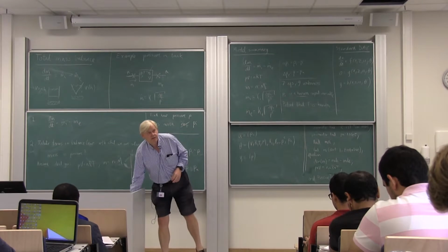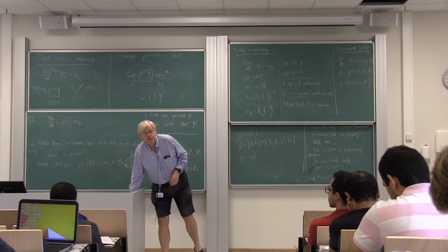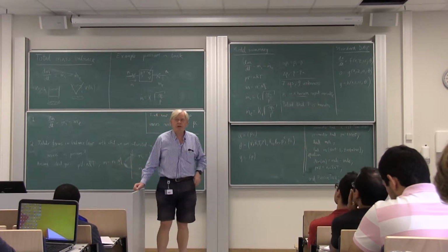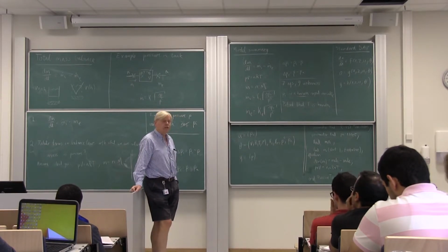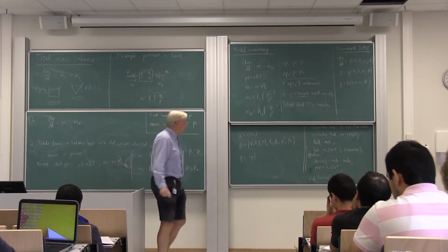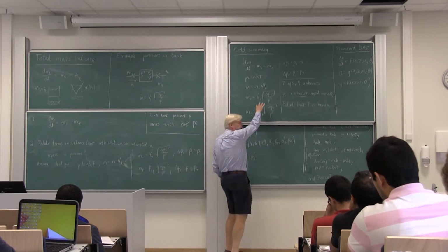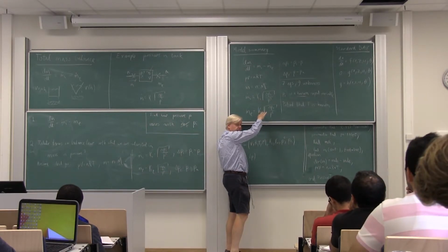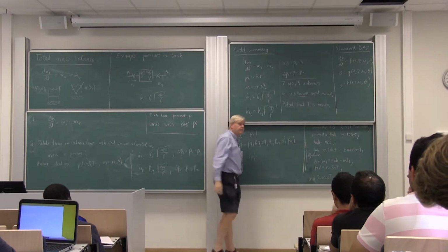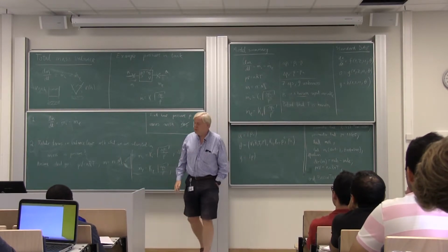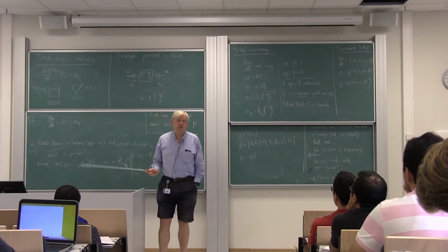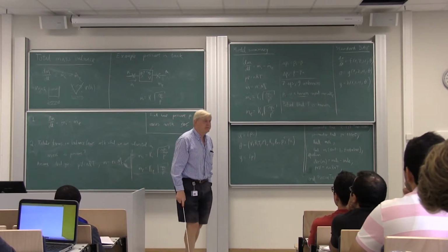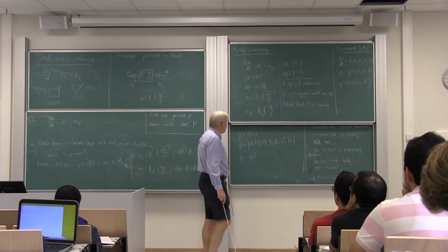So this means that if you want to formulate a dynamic model and then use OpenModelica, you don't really have to change the model very much. You can more or less code it the way you write it. So this works because Modelica supports differential algebraic equations and is equation oriented or equation based.